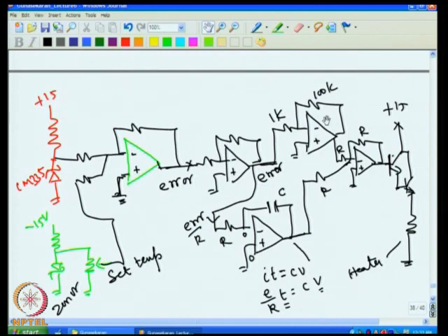So if we need a gain of 100, we keep a gain of 50 for proportional action, and then the system will not oscillate. Then we add the integral time constant. Since the gain is less, if proportional action alone was there, you would have got a lot of error. Because of integral action, now the error also goes off and the system stabilizes without any oscillation. So the gain should be set correctly like that.